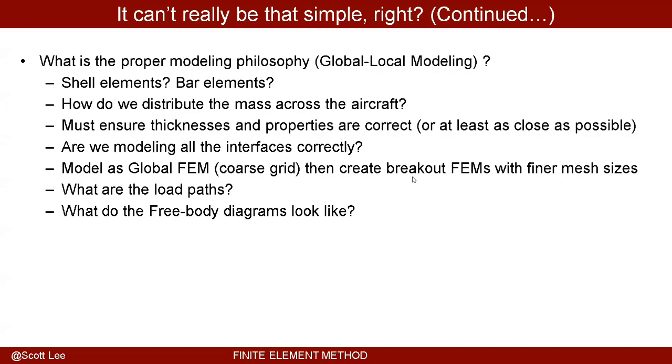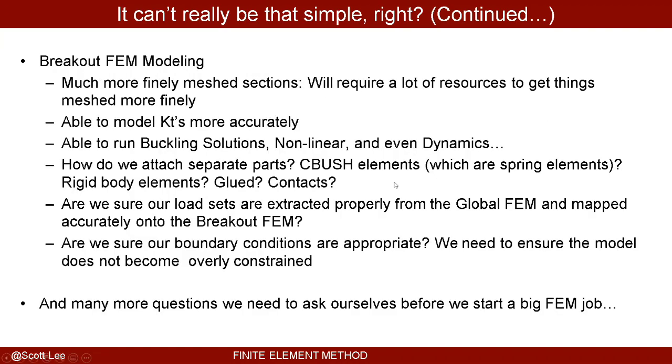As I mentioned already, we should model with the global FEM coarse grid and then create breakout FEMs with finer mesh sizes. Do we have accurate load paths? Do the load paths make sense? And what do the free body diagrams look like? Do the free body diagrams make sense? Any questions before I move on? I'm not going to go into these in too much detail, and I don't expect you to understand everything I'm saying. These are just examples of questions that I have to ask myself before I start a job.